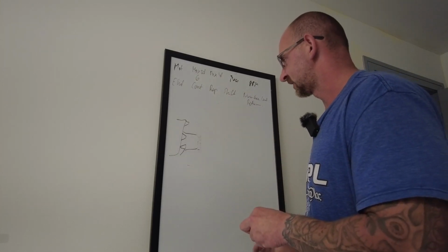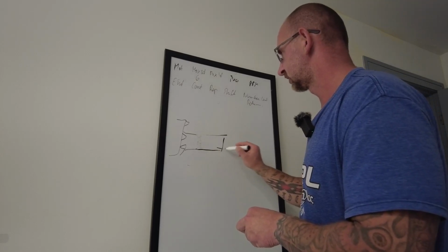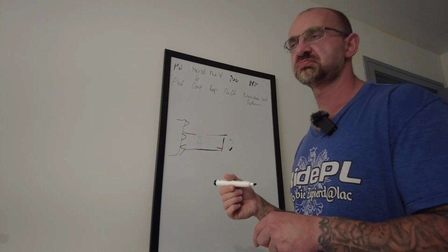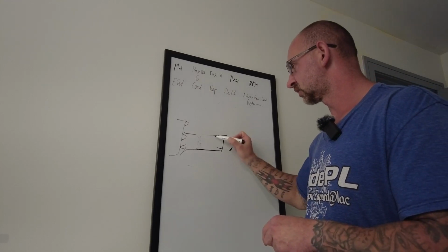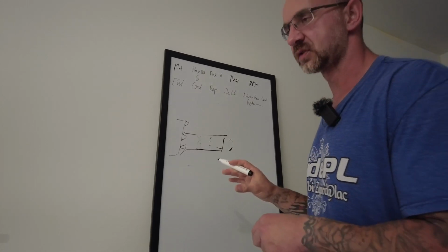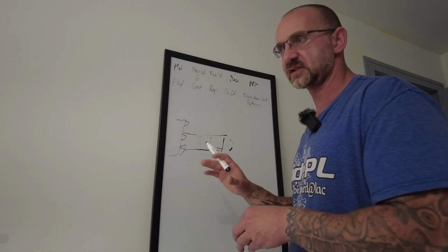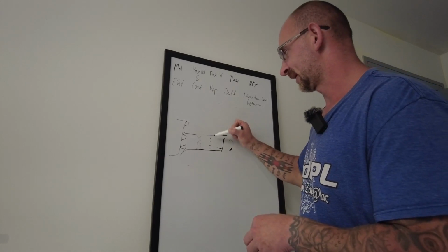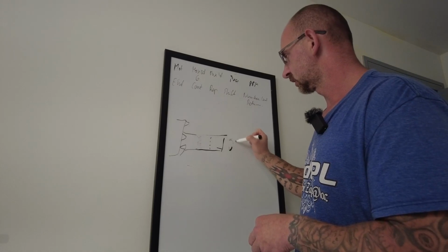where I use, for example, if I have a 2-inch part, and on some things it does it, okay, I've got a 2-inch part, and let's say you do milling, a lot of holes and whatnot. So for example, you have 10 holes you mill, and that's going to be in 1 unit, right? So you go 1 unit, for example, 6 holes, and then you divide your 360 by 6 holes. This is going to be the angle, and it's going to rotate that angle, and then it's going to come down. Then what's going to happen is, let's say the part is 2 inches, like previously stated, okay?